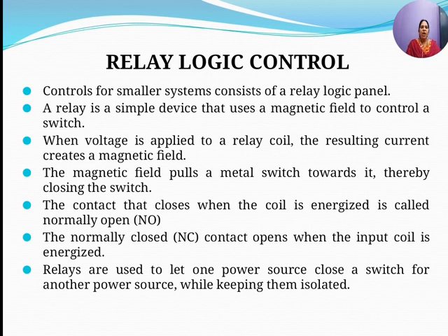When it comes to contact, it closes the circuit of the power supply to the motor. So what is happening? The motor is powered, the motor runs and the conveyor moves. Thus, the conveyor begins to move. So this is how you are going to use relay logic control.